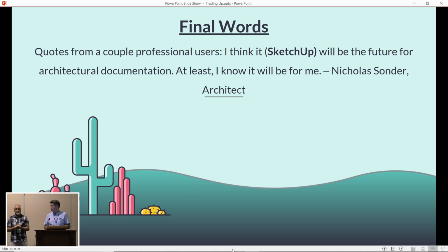I simply close my SketchUp file. I work in my layout file. If I come across a problem, I'll close layout, I'll open SketchUp, change it, and then I'll go back to layout and open it. As soon as you open layout, the fresh new drawing in SketchUp will reload in it. And if it doesn't, it's very simple under the pull-down menu, document settings, to reload that file. And it's definitely helpful to use both.